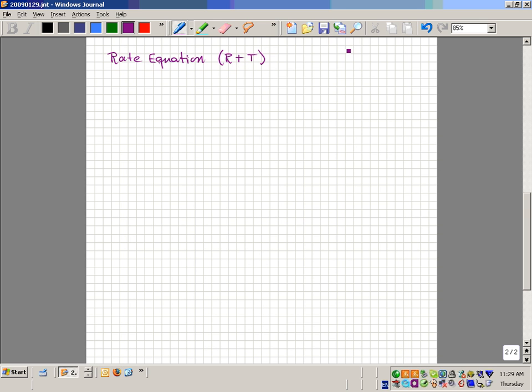We have a gas reservoir, a gas field, if you will, and the rate equation is B Q_W squared for a well, plus A Q_W, minus P average reservoir pressure squared, minus P tubing pressure squared, equal to 0. So this is our rate equation for a well.